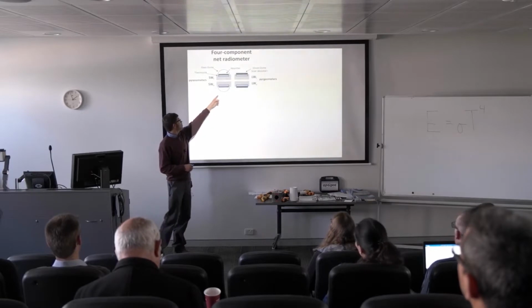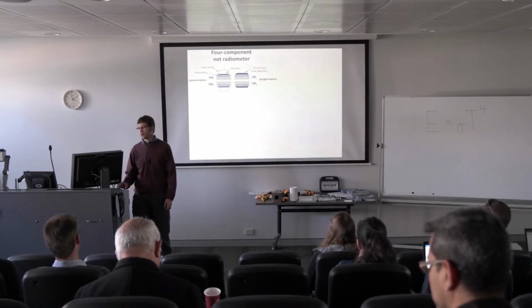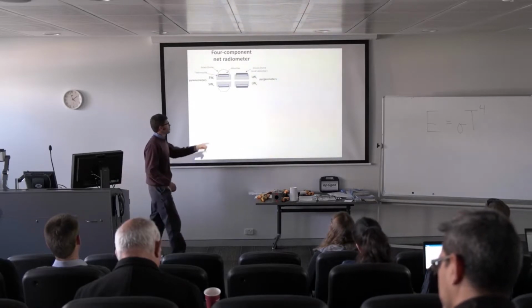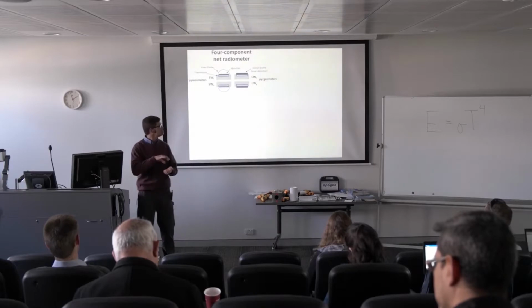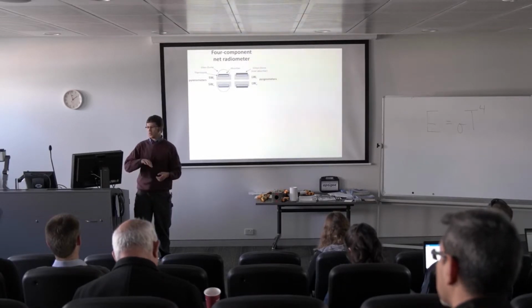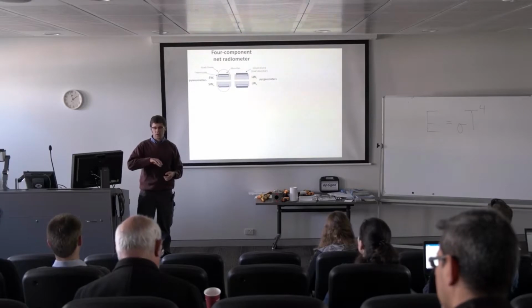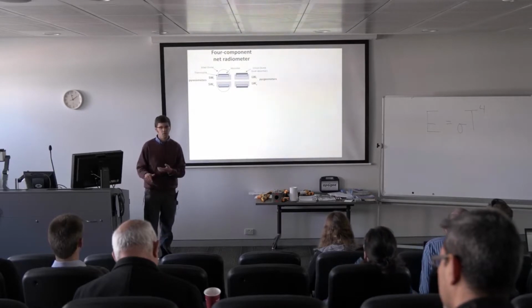So the downward looking pyranometer is the same thing, it's just inverted. It's one of them that's mounted upside down. The pyrgeometer is very similar. The only difference is instead of having a glass dome, it has a silicon dome over top of the black body. And I know what I've drawn here doesn't look like a dome shape. Sometimes the pyrgeometers will have a small dome shape, other times it'll just be a flat surface, so it's actually a silicon window rather than a dome.